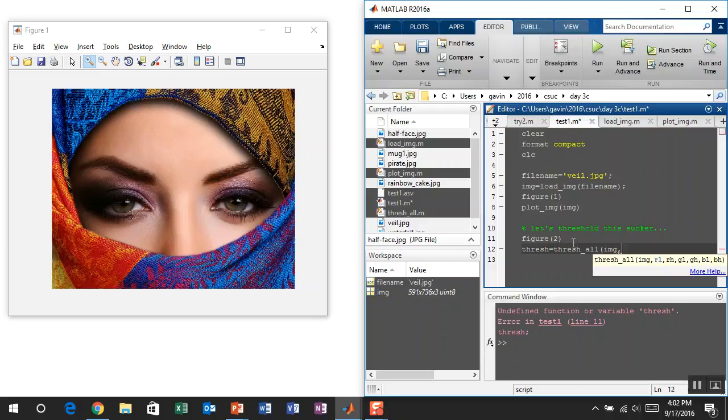Red low will have kind of a small, let's see if we can get most of this stuff, right? So we want kind of a high red value. So let's make the low part of the red threshold 200 and the high part 255. And then we'll make green all of them and blue all of them, 0 to 255 on both of those.